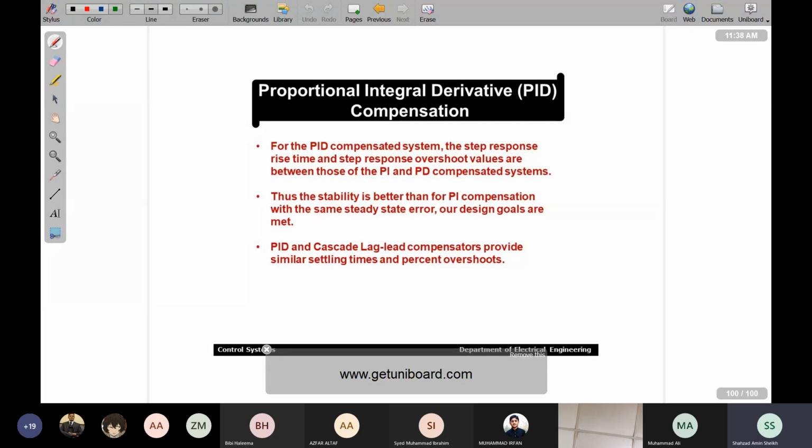Then we move to PD or proportional derivative compensator. The controller utilizes transmittance in its feedback. We discussed this a little while ago, and HCFS is equal to 1 plus AS, where capital A is the location of your zero. So this is in fact introducing zero in the system. Relative stability of the system increases, and we are interested in improving the steady state performance as much as possible. Finally, to combine the effects of PI and PD controllers, we discuss PID controller. This controller improves system type number, therefore the error performance of this system is improved.